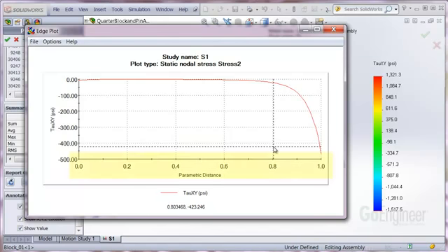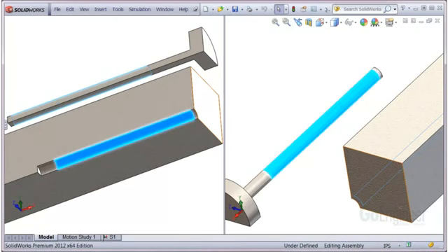The major vertical divisions have 20% spacing on the graph. So immediately you can see from the graph that most of the shear stress occurs in the first 20% of the bolt length, up near the head of the bolt. I used split surfaces on both the block and the bolt, which are matched in length. Here are exploded views showing the split surfaces on each component.